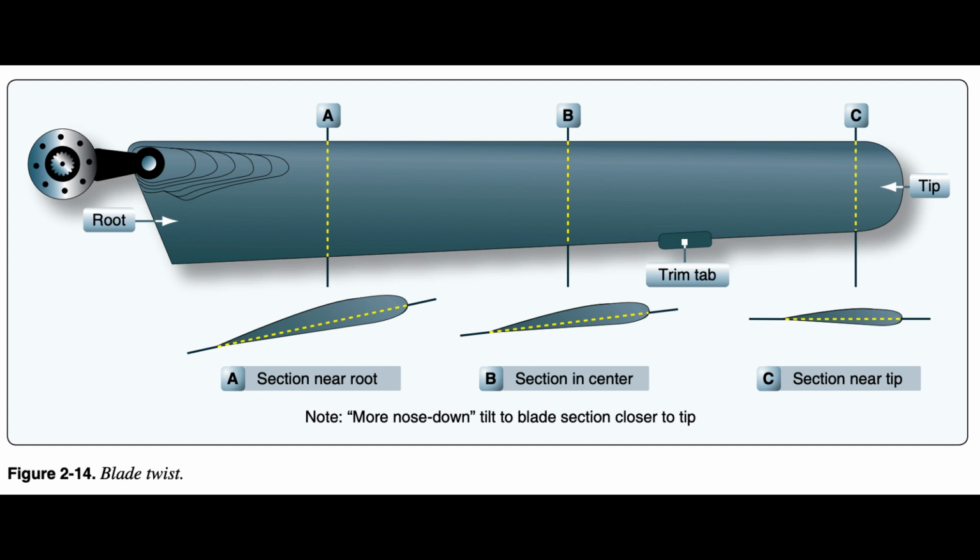The angular position of the main rotor blades, as viewed from above, as they rotate about the vertical axis of the mast, is measured from the helicopter's longitudinal axis, and usually from its nose. The radial position of a segment of the blade is the distance from the hub as a fraction of the total distance.